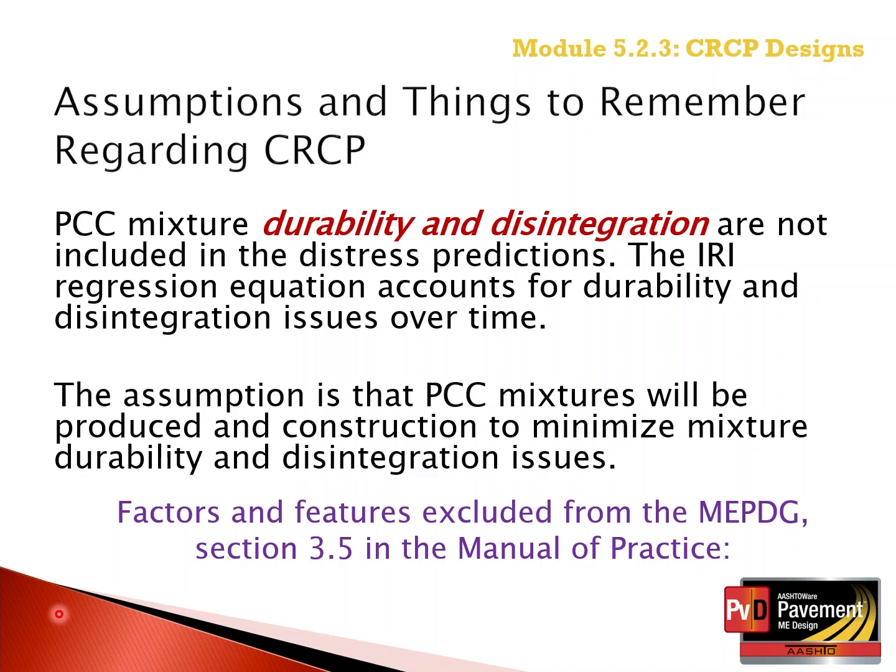As mentioned in the MEPDG Manual of Practice under Chapter 3.5, Factors and Features excluded from the MEPDG, durability and disintegration of the concrete layer, as an example, D-cracking, is not predicted by the software. It is assumed that the concrete materials and mixture will be designed and placed to prevent any durability issue from occurring throughout the design life of the pavement.